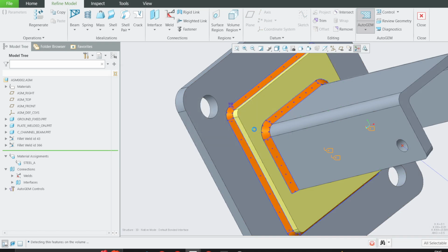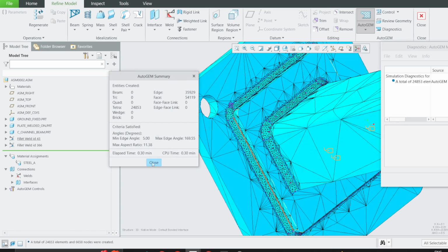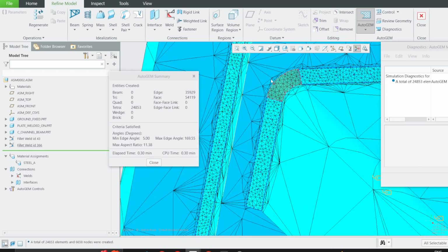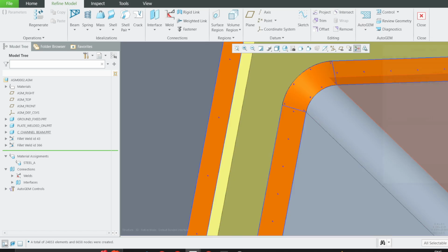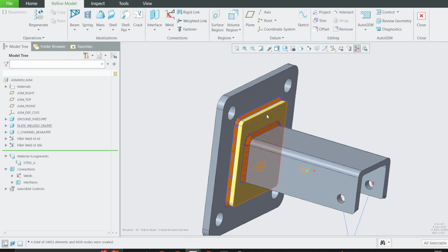If you now create this mesh, let's see, you see now the mesh for the weld solid will be 2 mm smaller in size, so that you can get more accurate results on the contact surfaces here. But for the rest of the geometry, you don't need to refine. You can see now the model has refined. You don't need to save this. I just want to show you that it is possible for you to refine the mesh.